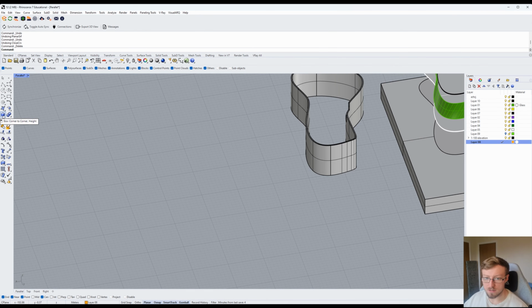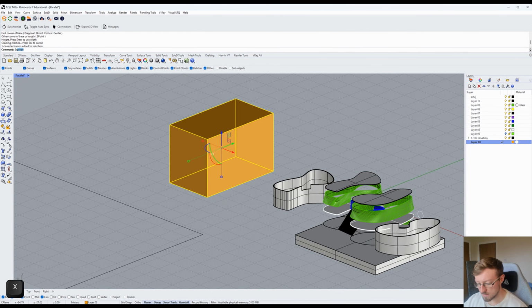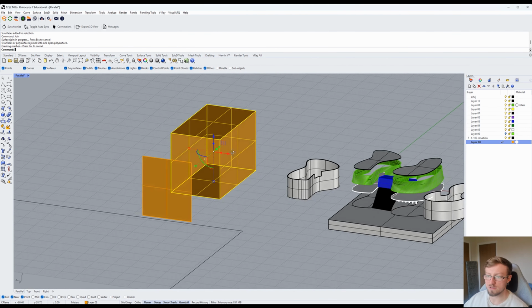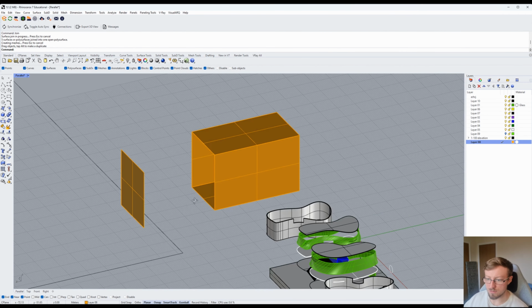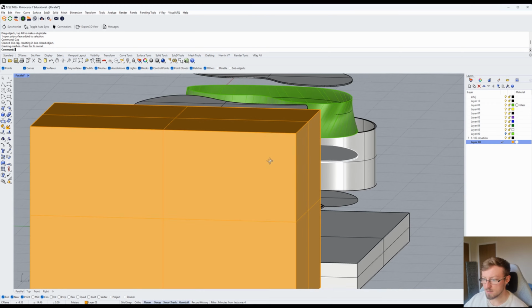We can cap, which we'll do this. If I just do that, we could explode it to get the individual faces. If I move that and now I join, that'll create a geometry from them. Now we can press cap, because this face is open, so if I wanted to create this into a solid, I press cap, now that'll close that.